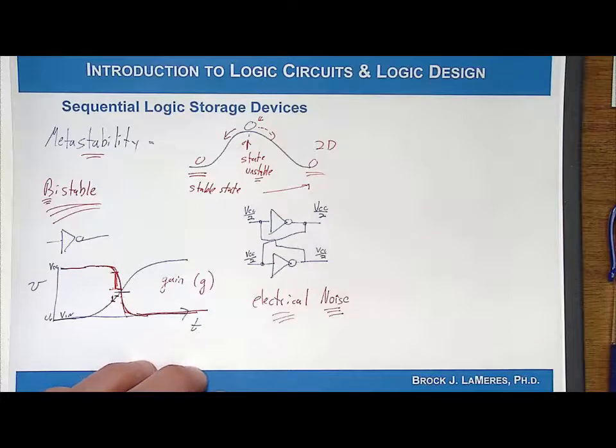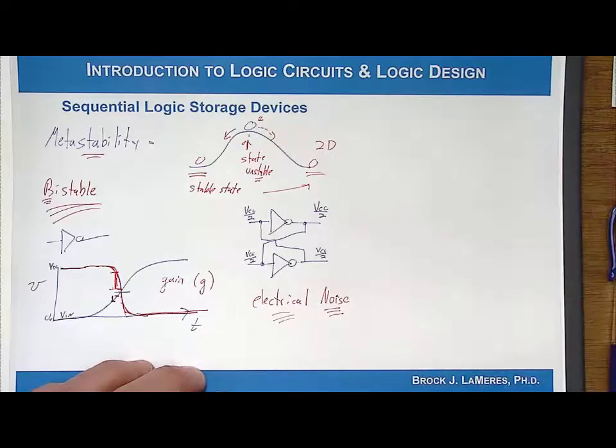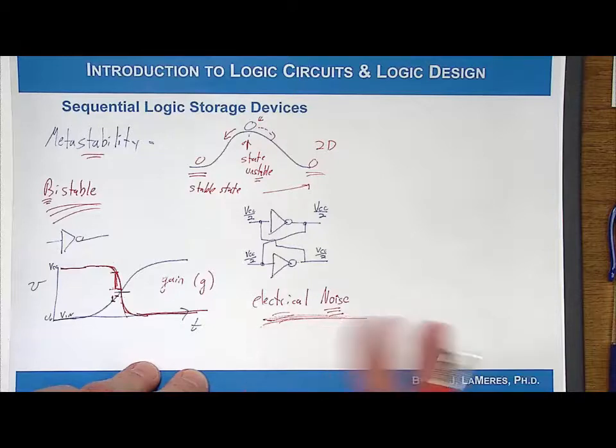So if a material is not at absolute zero, you have motion in the electrons of the atoms in there. So you have electrons moving around. Unless you have a perfect material with no resistance, you're going to have current moving through a resistance, and that will produce a voltage. So thermal noise is a very common one. There's tons of different types of noise in electronics, but it's always there. And it's a random noise, so you really don't have control over where it comes from or what its shape and magnitude is.